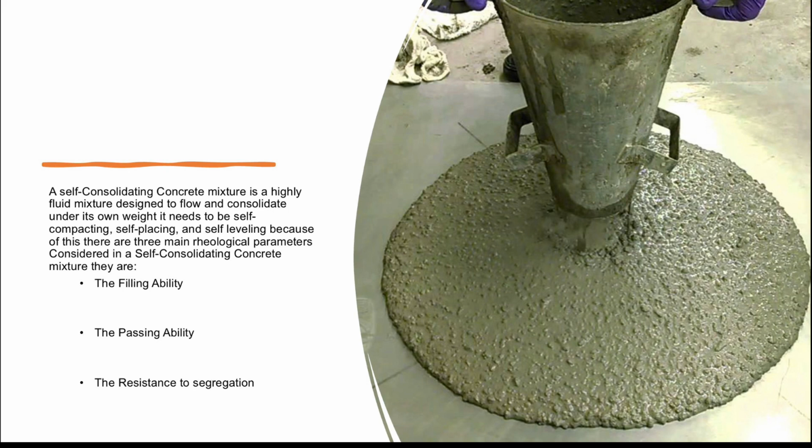Because of this, there are three main rheological parameters considered in a self-consolidating concrete mixture. They are the filling ability, the passing ability, and the resistance to segregation. Let's talk about each of these rheological parameters individually.